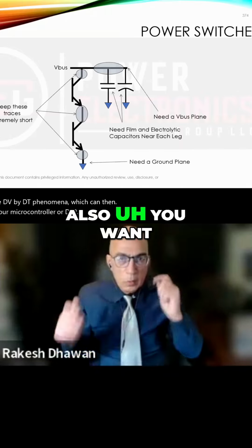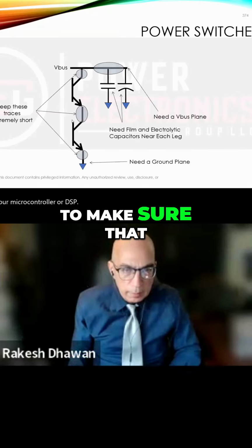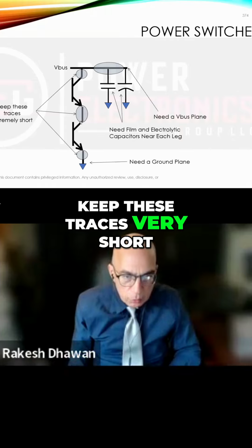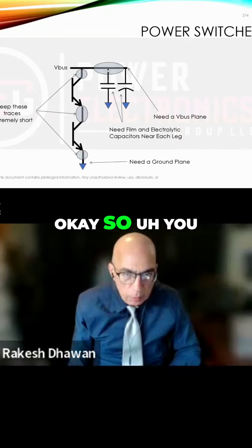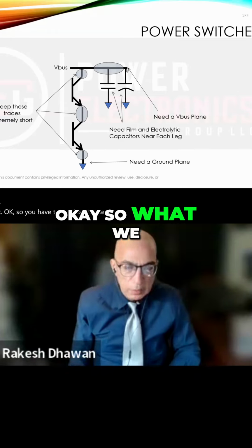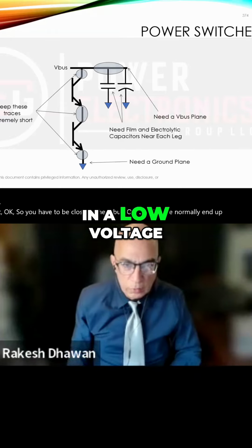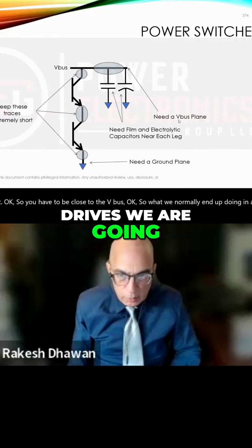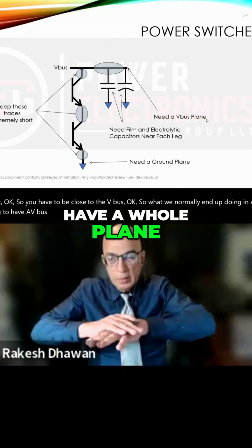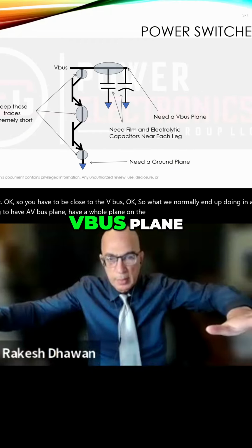Also, you want to make sure that you keep these traces very short, okay? So you have to be close to the VBUS. What we normally end up doing in low voltage drives is we have a VBUS plane, a whole plane on the PCB, which is called a VBUS plane.